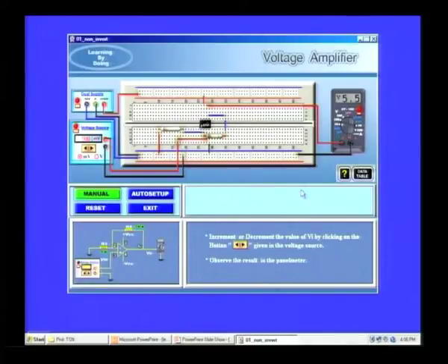You would also observe that the same circuit, if I have to do it with transistors, is much more complicated because the transistor is a more non-ideal device, whereas an operational amplifier is very close to an ideal device. Therefore you would find the design of the transistor amplifier much more complicated, and that is why you have to use an H parameter or an R parameter or a Z parameter, and you have to make a lot of approximations, analyze the circuit and then design, and then finally you may find that the design will not lead to very high gains unless you have multiple stages.